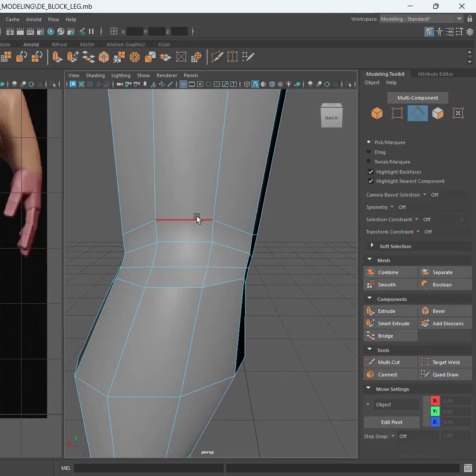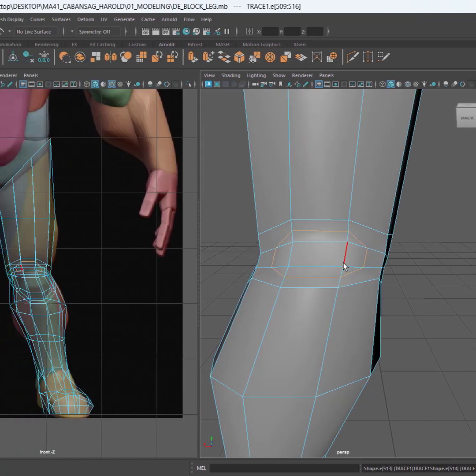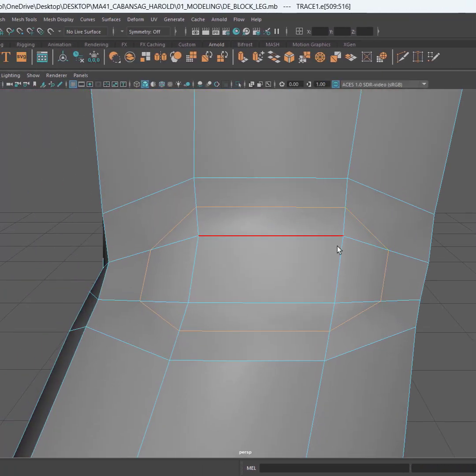I can also do it this way if you prefer. I can select these surrounding this part, do a connect, Q, there. This is another way of doing the patch also. And then I can select the multi-cut tool, shift and snap onto the center and cut to the vertex here. Q. That's another way of doing it. I'll do it again. Shift, connect here,